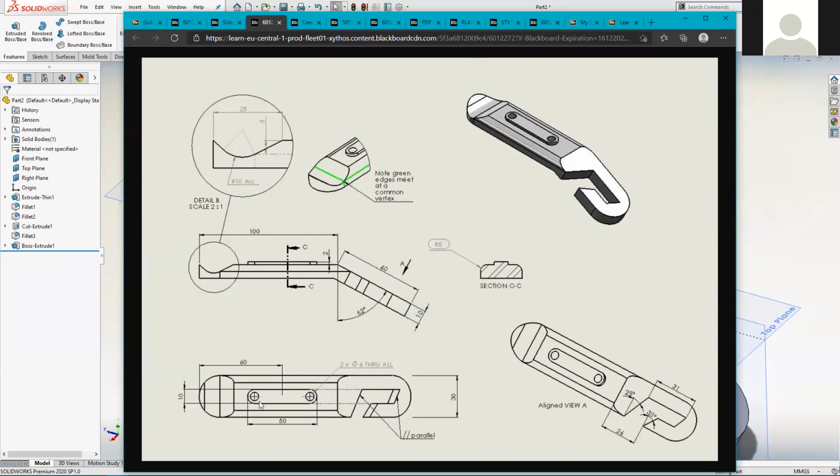And I mean, what we could do is just read that spec on them and translate that to a circular extruded cut that we put in. But the fact that the drawing that we're looking at here, that was also generated in SolidWorks, has put that annotation on them, suggests to me that the model was modeled using something called the Hole Wizard.